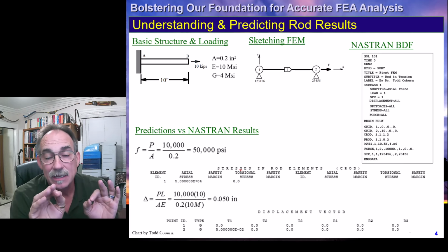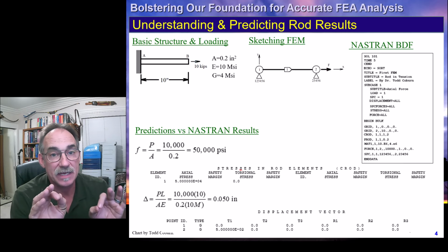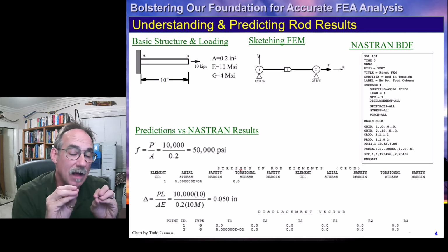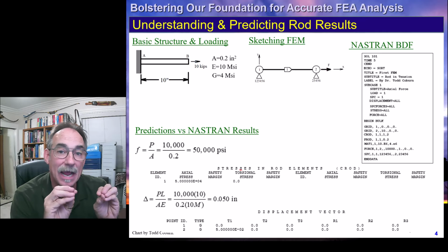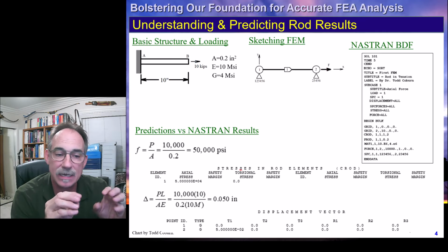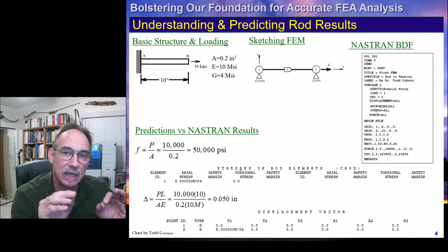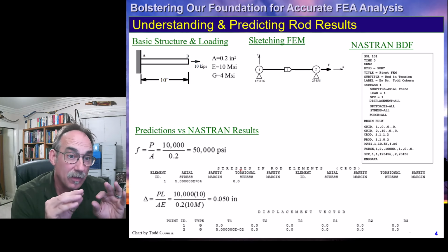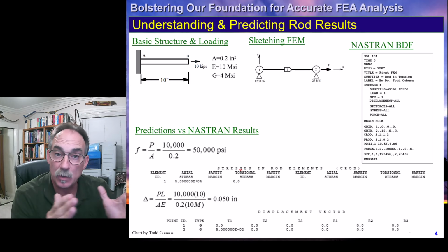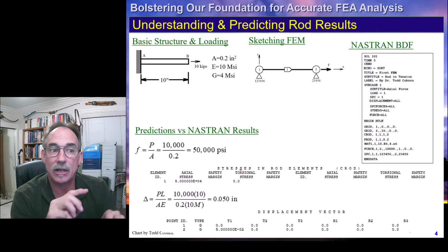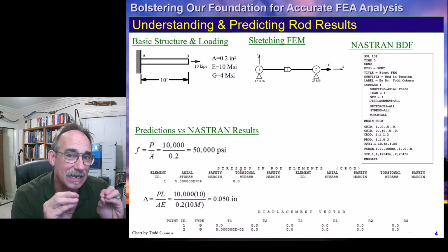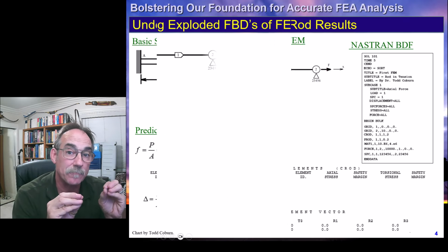Actually many or even most margins of safety for practical structures are going to need to be hand processed, because NASTRAN just cannot calculate in a reliable way the margins of safety that we need for practical analysis without a lot of very detailed and different finite element models for a given piece of structure.